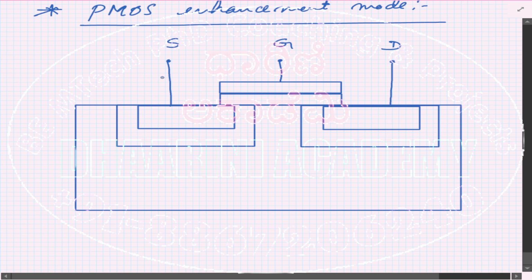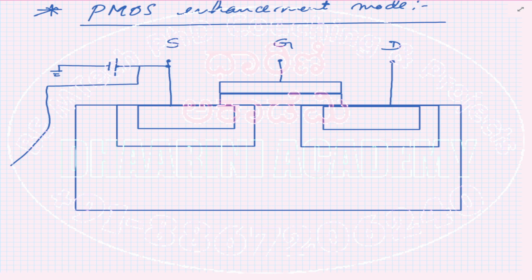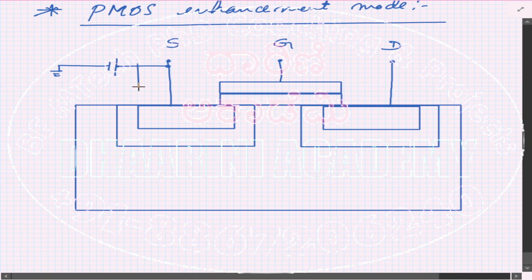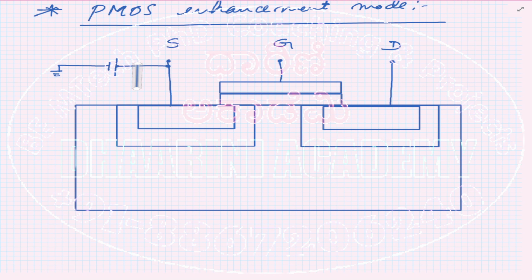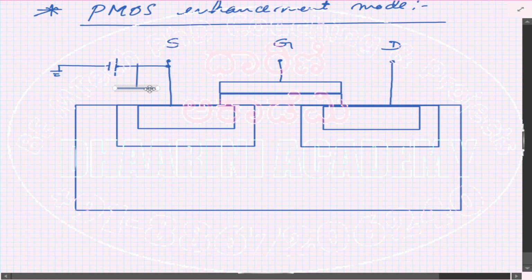All right. Now, as per our discussion, we know that there will be a positive voltage connected to the source, correct? So plus minus, this minus I connect to ground, but I am connecting the positive terminal to this. At the same time, this itself needs to be connected to the body of the MOSFET, correct? It is grounded, correct?